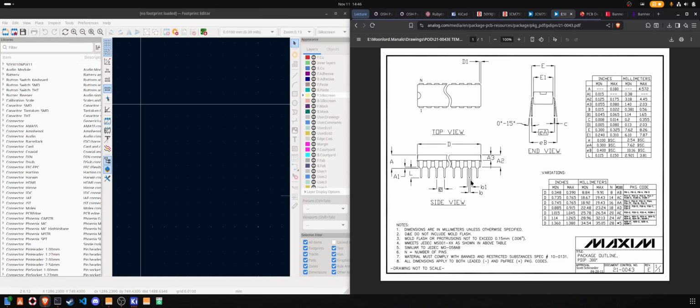and then we're going to be placing our vias as through holes so that we can actually mount this chip on the board, and we need to know how big the drill hole is for the via and how big the pad size is that you're going to be soldering onto, and this is where IPC comes in. So as a general rule of thumb, whatever the lead size is for this IC, we're going to be adding 0.25 millimeter. That's a good rule of thumb for doing through-hole designs or any just SMD design.